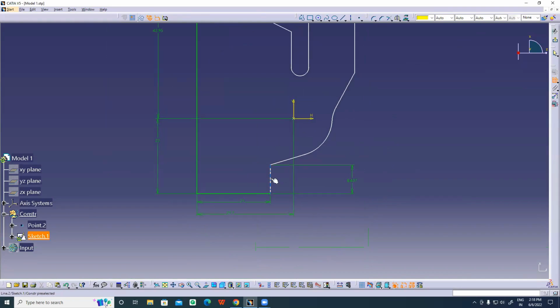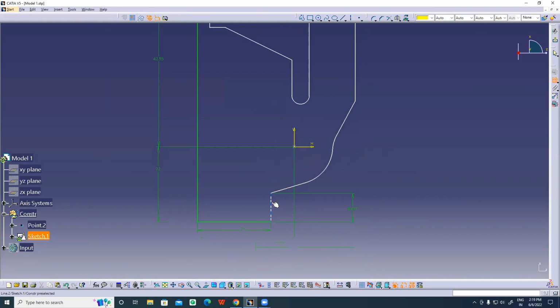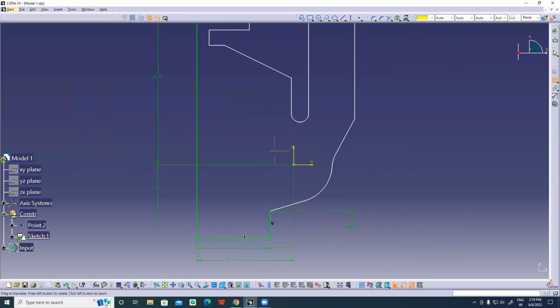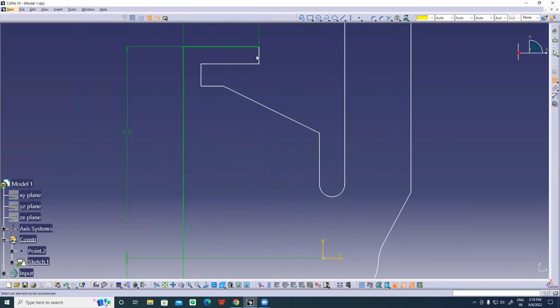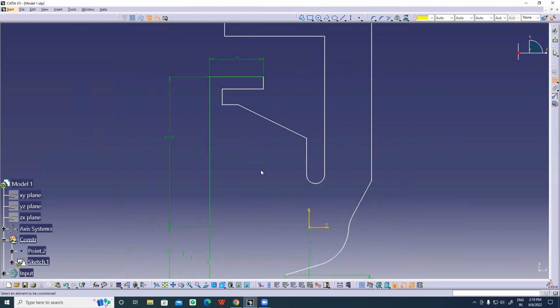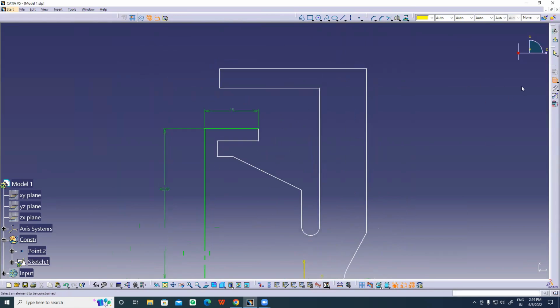And you can see this portion after applying a dimension also it's not coming, right? Select this line, right click and apply the vertical relation. Previously you might be using, to apply a relation, selecting one line and using this option, Constraint defined in the dialog box. But actually you don't need to use this option, guys. When you're just using a dimension, directly you can do this.